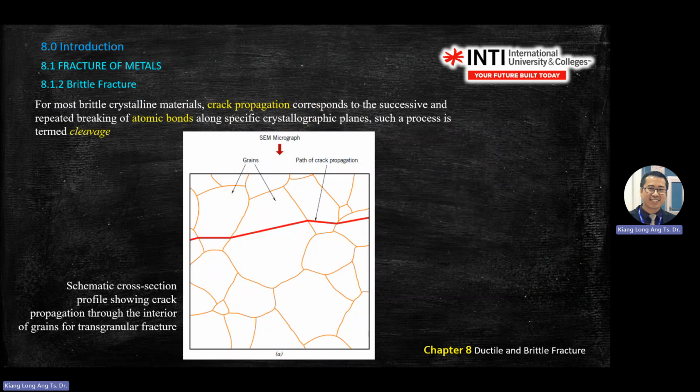How did it happen? Because of these grains. Between the grains there is space, so it will crack along the grain boundaries. Okay. So from this you know that the direction of force is perpendicular to how it cracked. The force is like that. The rest you read.